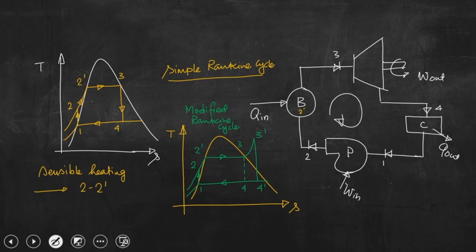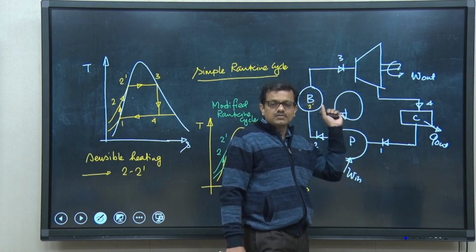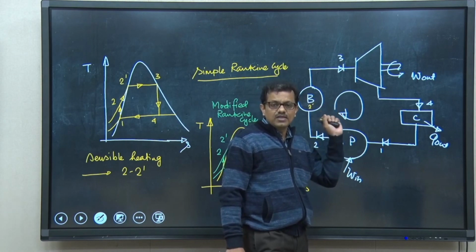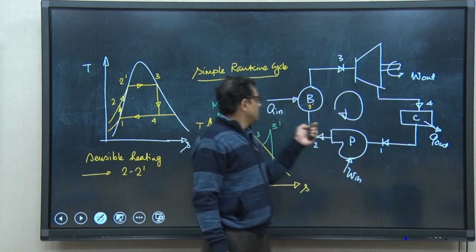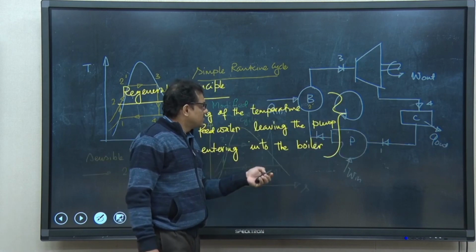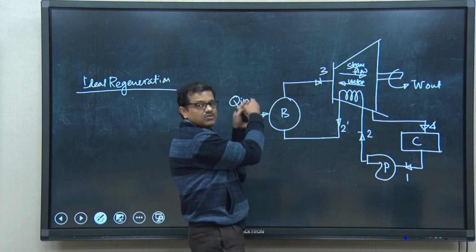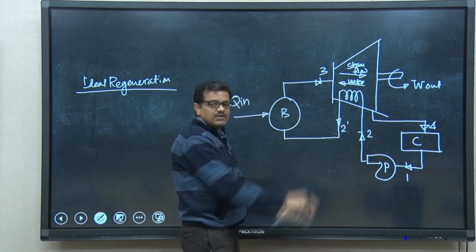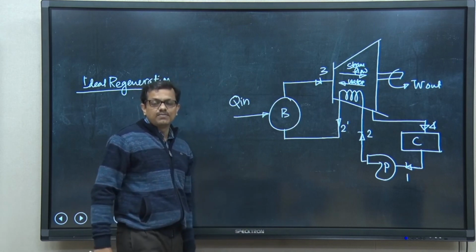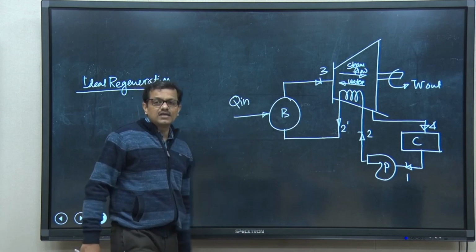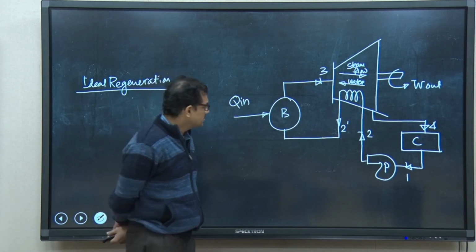particular case. So, if we consider the size of the plant is the same, and the mass flow rate of steam per cycle is also the same, to get equal power output, if we compare this arrangement with this one, we can understand that the heat which needs to be supplied to the boiler for this particular case would be less, and we can increase the efficiency of the plant, because thermal efficiency is essentially a function of Q out and Q in that you have seen.